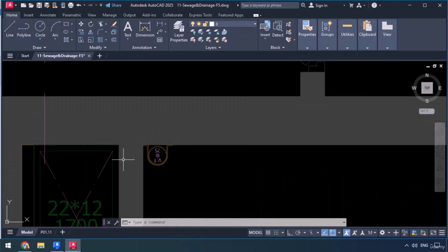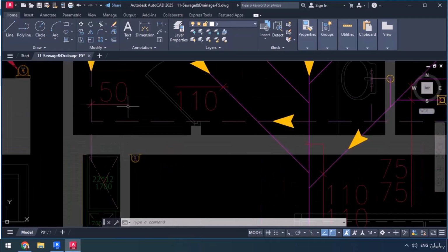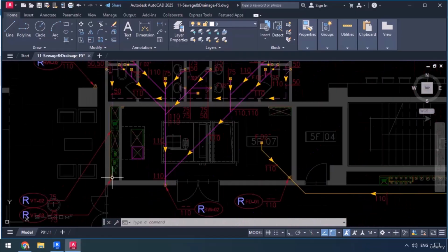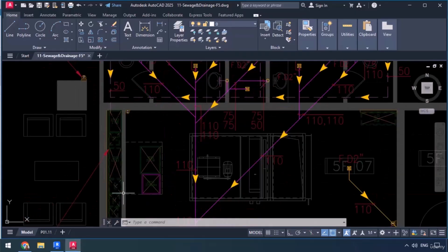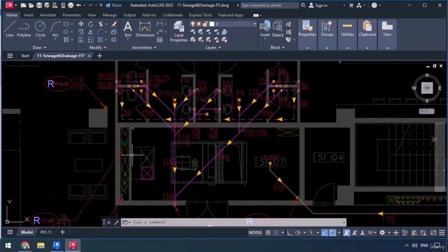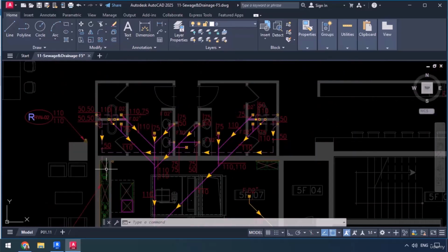Here is our riser vent, but its position is a little different in the plan. So in the model, we're going to be drawing this way, because if you look over on this side, we've got some ducts and duct risers. Now we do have enough space for some other vents to lead here, but as for this vent riser, it's going to have to be repositioned to here.